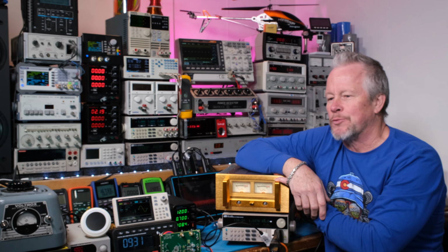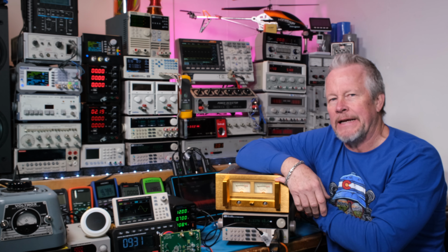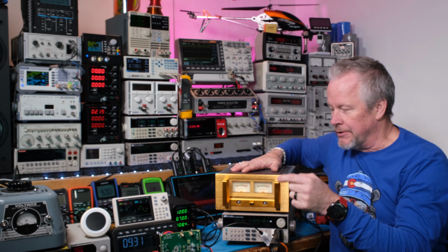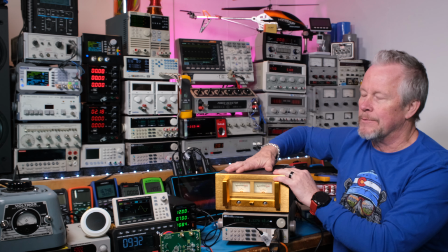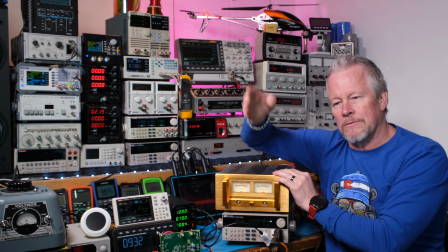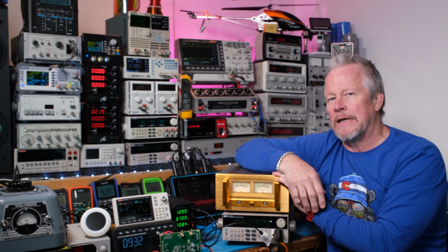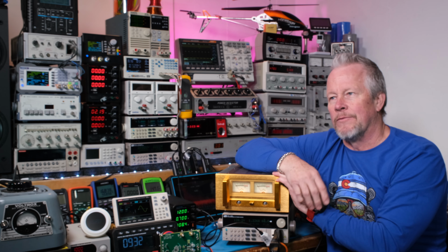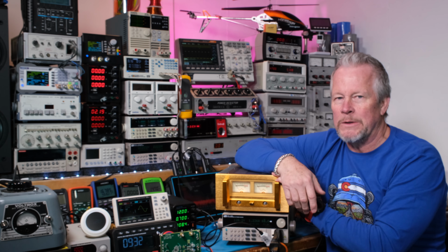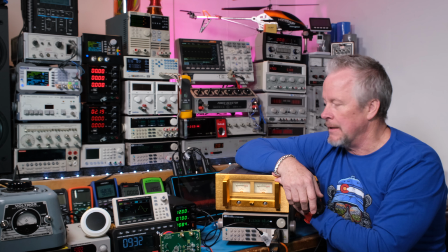So that's why I think it's important to understand that these are all switching power supplies. These are low frequency switchers. We've seen the switching, right? The diodes are commutating. They're turning on and off, causing these spike currents. You don't get current in a sinusoidal fashion like the voltage coming in. The voltage comes in sinusoidal, but the current is pulsing, switching on and off.